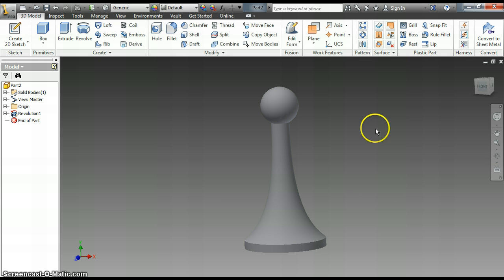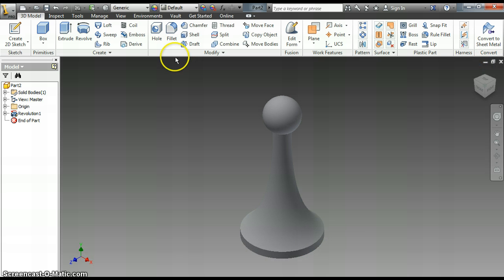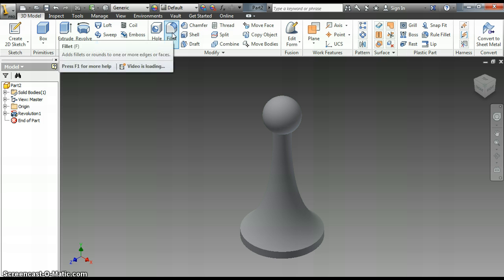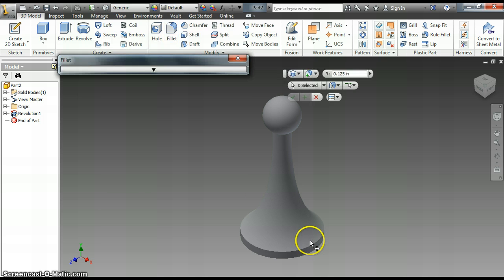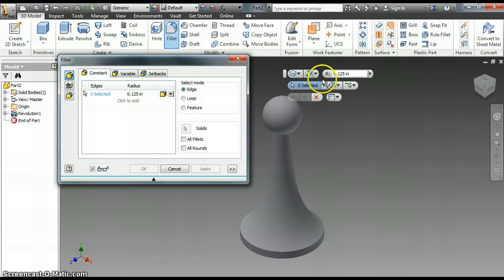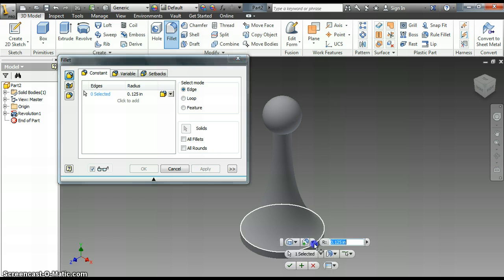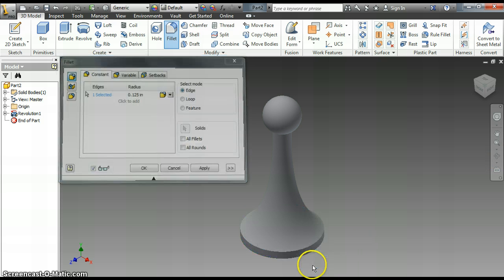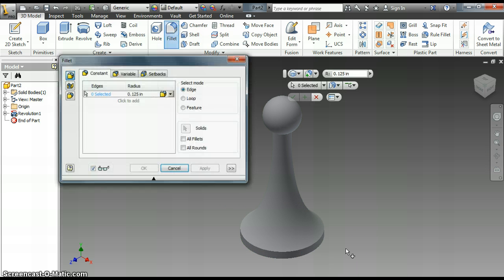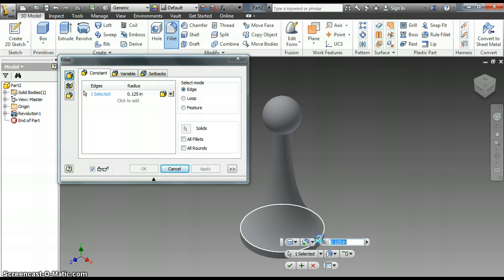From here, though, if you're making this for a client and it's a children's game, we've got a lot of sharp edges on here, so we're going to have to use the fillet tool. Fillet tool is here, and what that does is it rounds out some of those sharper edges. So I'm going to click that. In the drop-down box, we see the radius of the fillet. Because we're working with a small piece, when we click it, a 0.125 has a very drastic effect on that. So if we do that again, fillet, look at from how sharp to how round that goes.